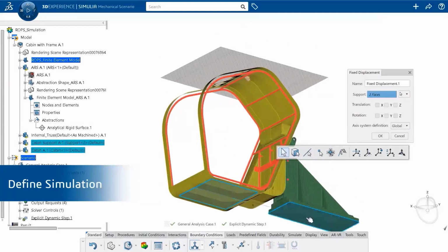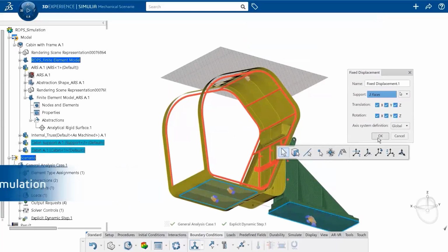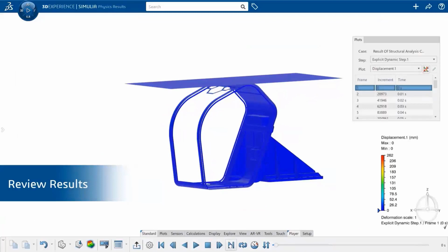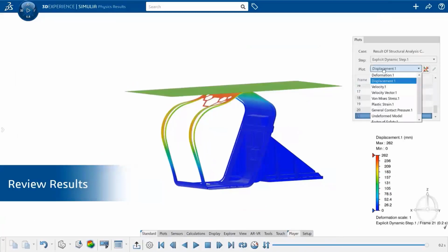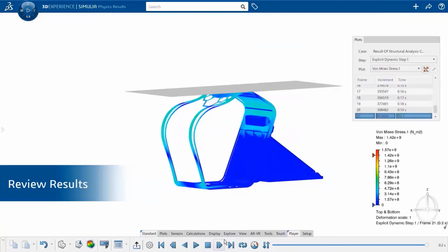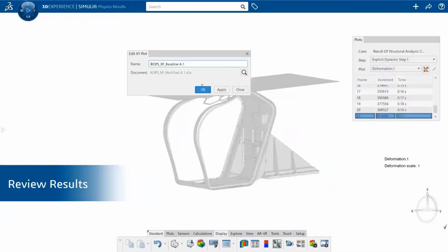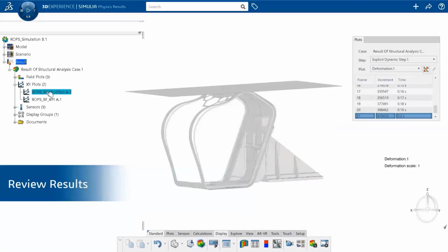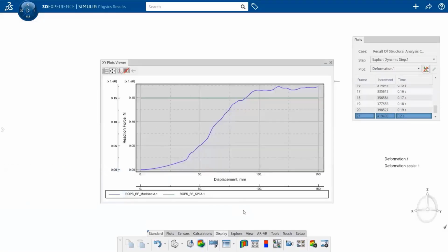We will push the top sheet metal, let's say the top plate, 150 millimeters down. And here we can see that the geometry is really deforming a lot. You can see we have some advanced behavior on the front tubes. We can get, for example, the reaction force to push down the cap.